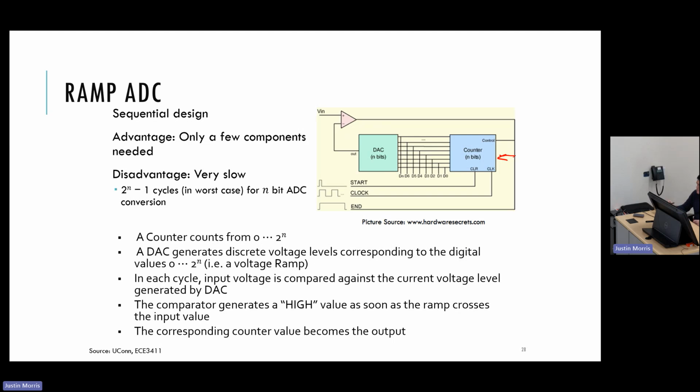And then based on the counter value, that's going to be input into this digital to analog converter, and it's going to output the value of the thresholds, one threshold at a time. So it's going to start at 0. Then if we go back to our other example, it would output 1, then 2, then 3 volts, and so on.